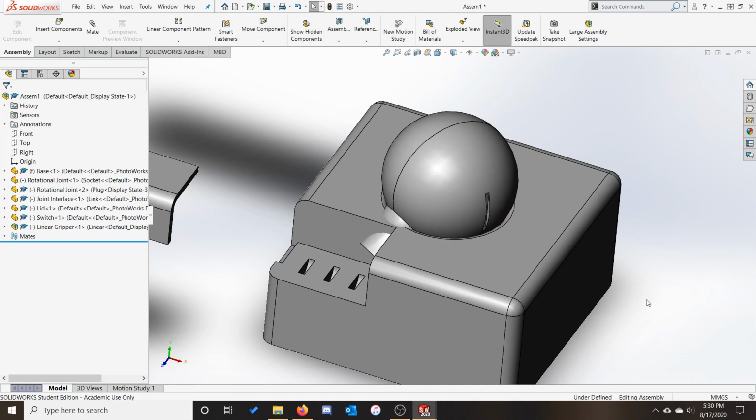This means that pieces of your assembly can intersect with one another, and it's up to you to provide the proper advanced and mechanical mates to stop the collisions. Of course, depending on your application, it's often okay to allow for the model to self-intersect, but you want to make sure that parts aren't clipping into each other in the assembly set you turn in.